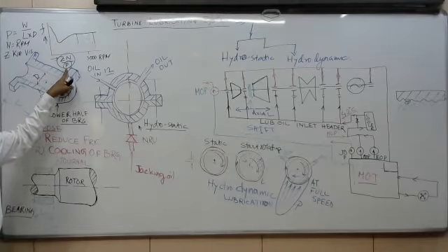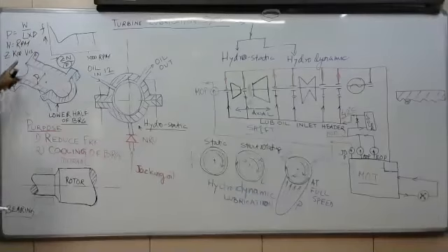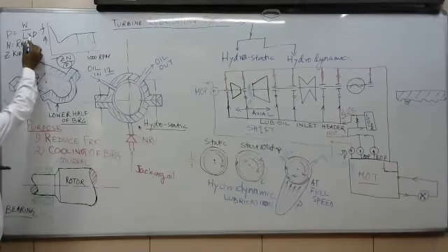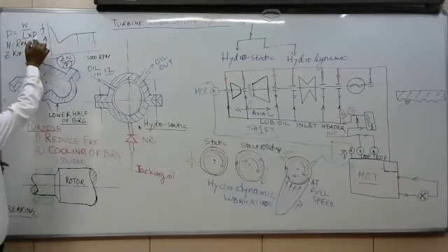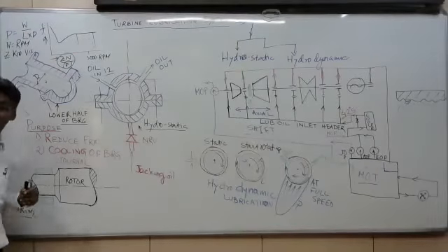P is the load carried by the bearing. P can be developed by the weight on the particular bearing divided by the length of the bearing times the diameter of the bearing. That is weight divided by area. That is the pressure, the load carried by this bearing.